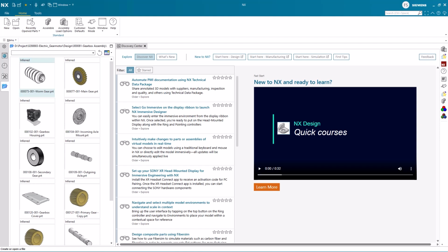You have also seen how to configure columns in the Assembly Navigator that provides easy access to crucial attributes in the configurable columns of the Navigator. We have demonstrated the typical folder structure to keep your project organized. And finally, we have set the system up for easy access to the project folder by defining a palette that can easily be used for drag and drop. This concludes this how-to session on preparing to build your first assembly.